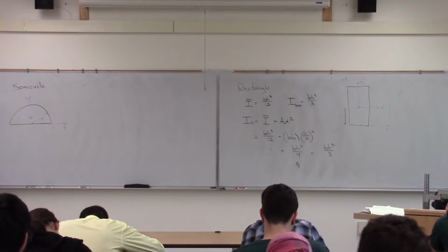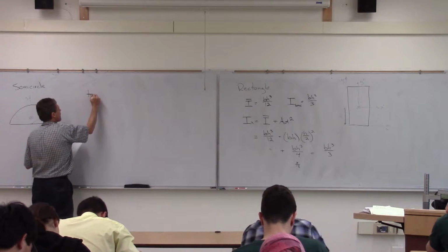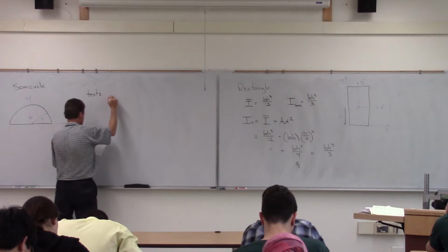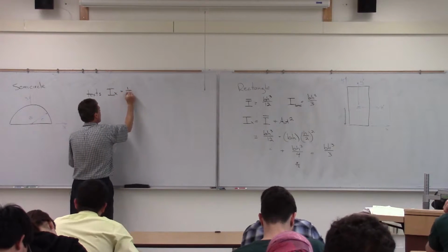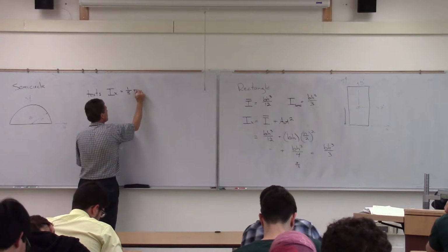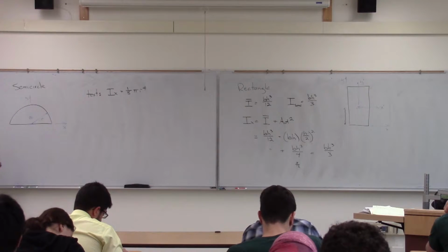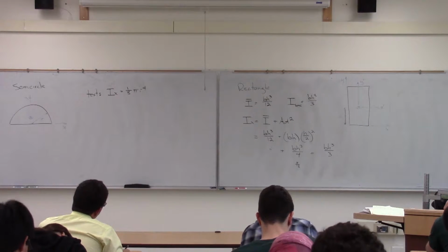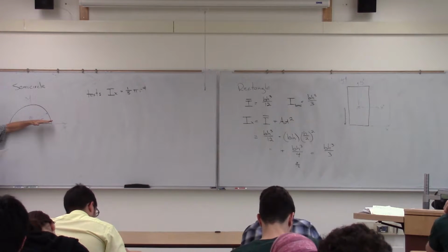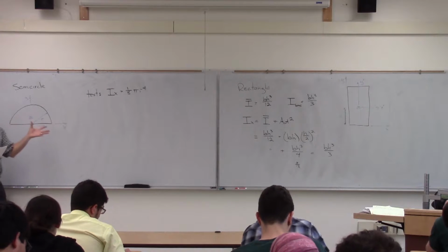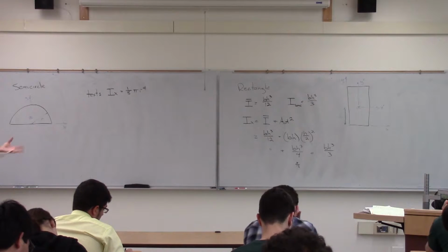So in the back of the book, in the text, we're given that. But that is based upon a moment of inertia about this x-axis there. So one of the issues I have is I can't use that in the parallel axis theorem, because if I need it in the parallel axis theorem, I need I bar.